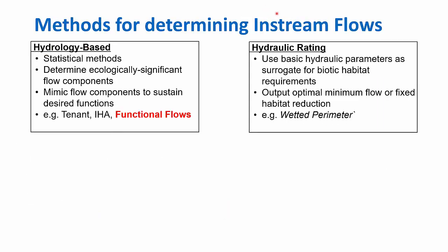The hydraulic methods look at the arrangement of velocities and depths throughout the river corridor, and at a given height, you're going to have a range of velocities and depths that will be beneficial for the environment.